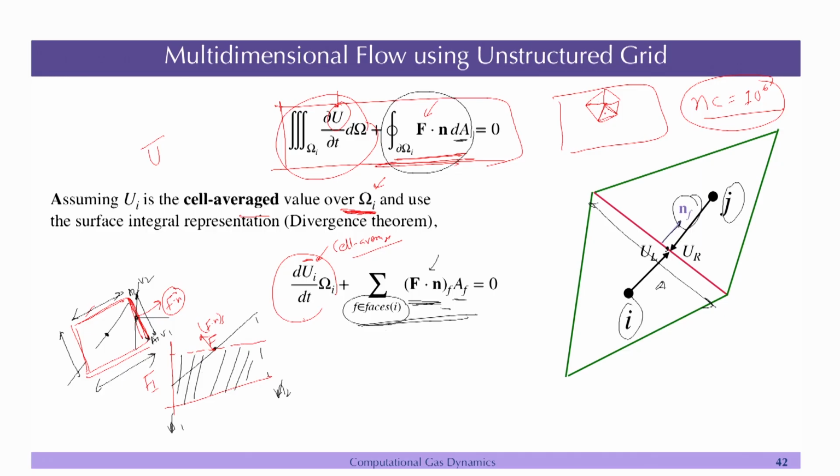So, for example, let us say my vertices are V1, V2 and V3. If you have made a cell which has counted as V1, V2, V3, then it goes from V1 to V2, V2 to V3, and the normal is in the outward direction. If it is going from V3 to V2, then the normal will be in this direction, right. So, you have to follow one direction. You cannot keep on changing. Many times when you create a mesh, what happens is that let us say you create the boundary mesh in one direction and the bottom in a different direction. So, sometimes you will have these issues coming up. So, you need to take care of that.